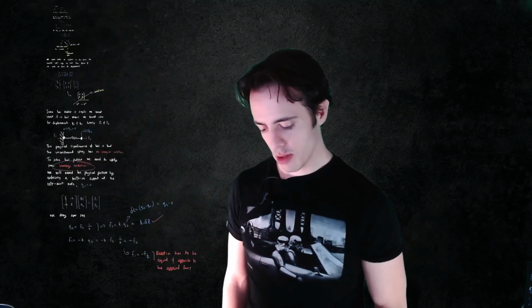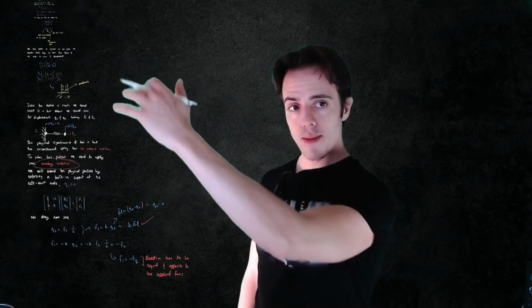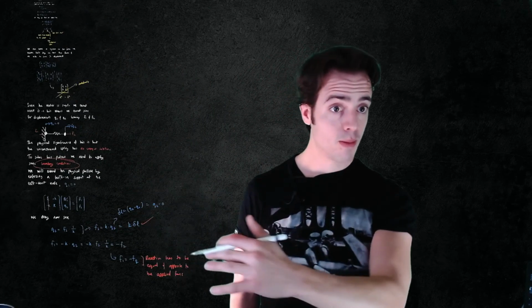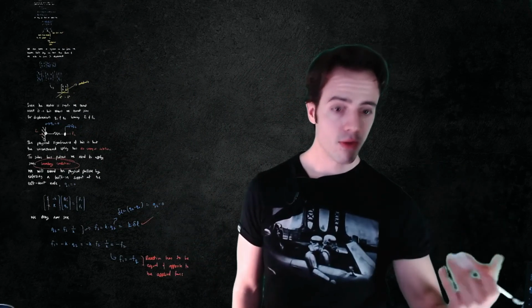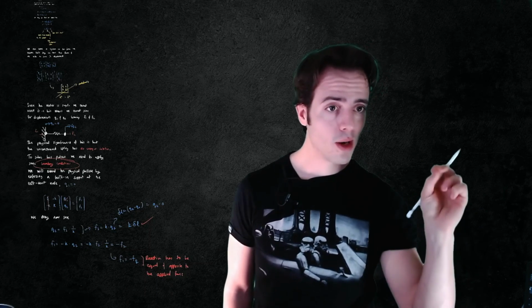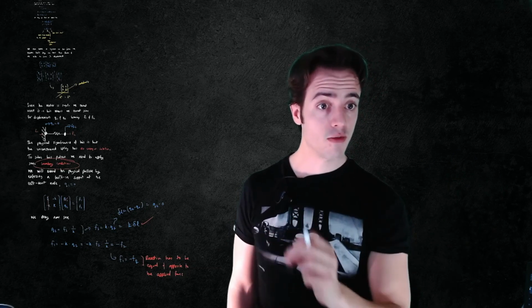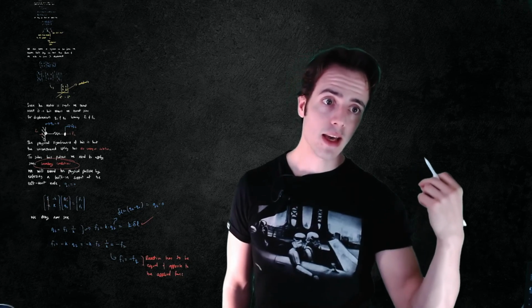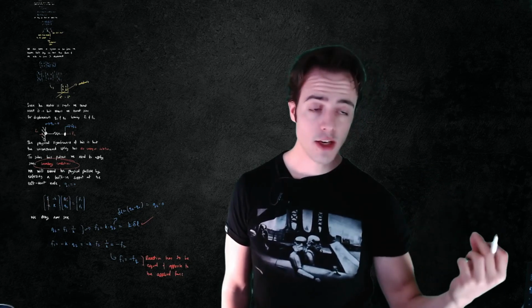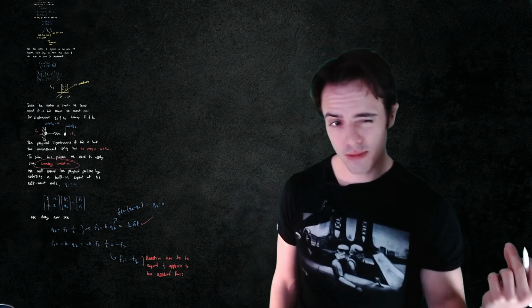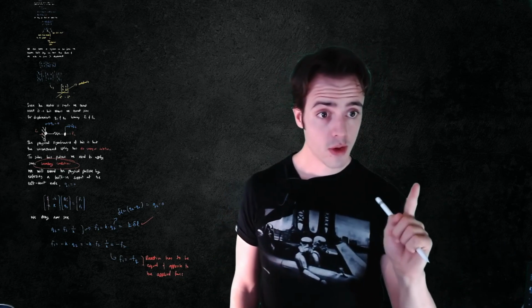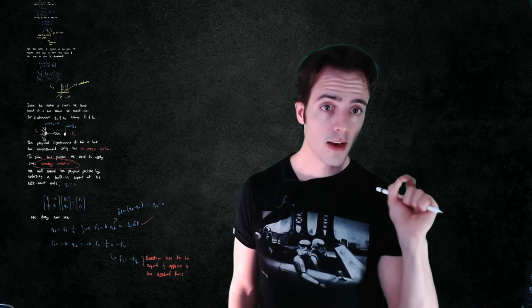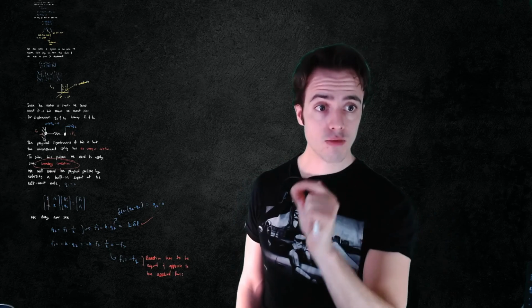Now, that might sound like we've gone through something just for the purpose of it, but we've gone through this methodology to show you how we produce a stiffness matrix for a single element. We've put it into matrix form and shown that we can't solve it without boundary conditions, but importantly, when we solve it, we get an answer that's physically correct.